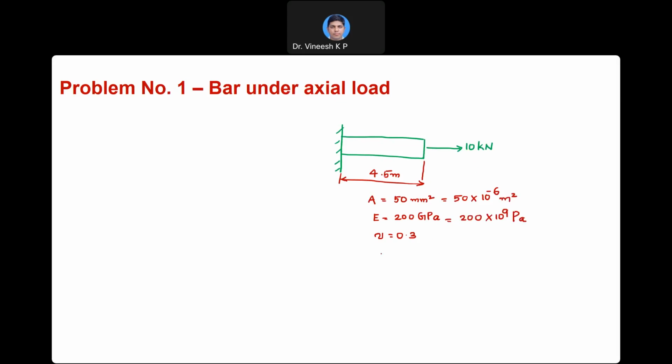Then the load, let's say we are going to apply a load of 10 kilonewton, so it is 10,000 Newton. So this is the problem in your hand. So basically the stress is equal to force divided by area. That is equal to, in this case, 200 megapascal.